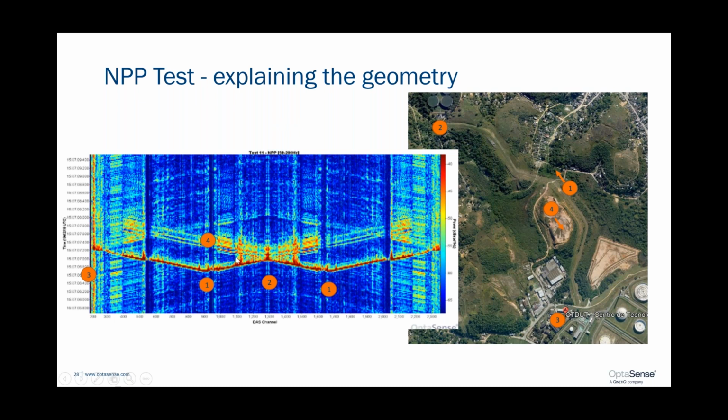The interesting part as well that we should note is if we look at the second observation for it here, we see that the pulse goes back to the bottom, point 3, which is at either end, and then comes around the flow loop and starts traveling back up the other pipe. And similarly, from the top, it also goes up to the bend and goes round the other side as well. So on these 2 sections, we're actually viewing the leak in the second part of the pipe, the downwards pipe, which is about 1.5 meters away.